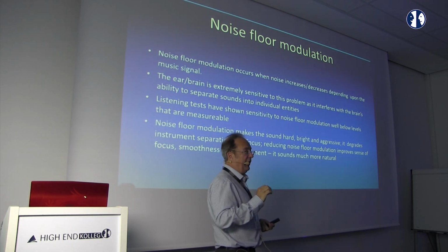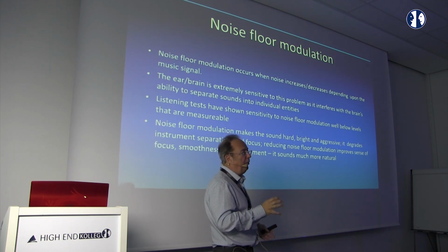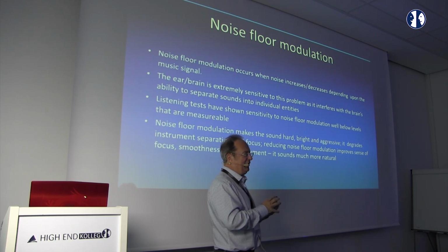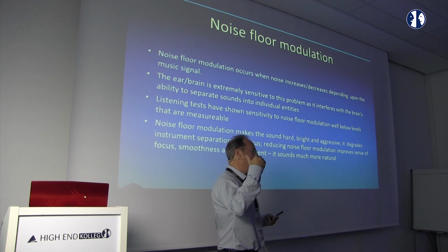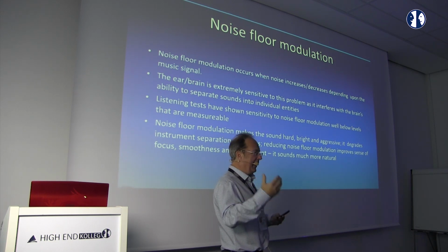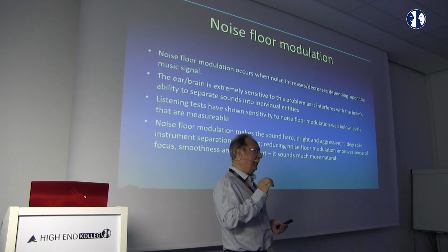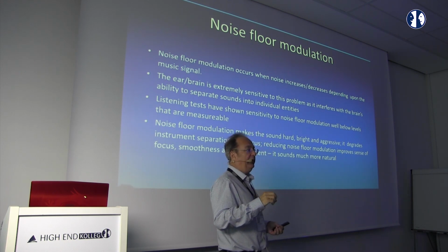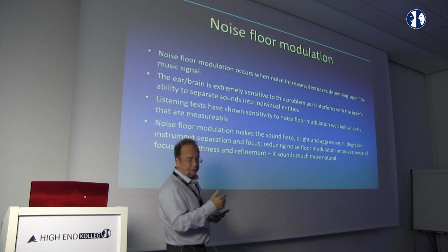So this concept is very, very important in terms of DAC design. The problem we have with DAC design is that noise floor modulation is a huge problem. You can get it from jitter, you can get it from the architecture, you can get it from RF noise, you can get it from the analog sections. There are a hideous number of ways of creating noise floor modulation. So trying to eliminate it has been something that I've been working on for a very, very long period of time. And I'll be showing you the results later we got with TT2.